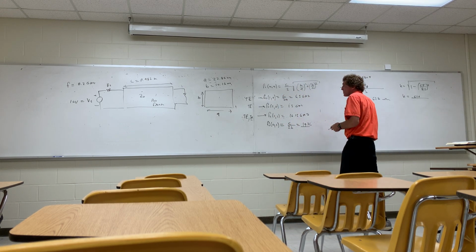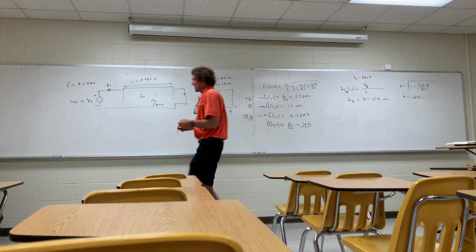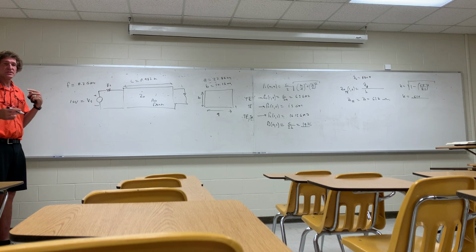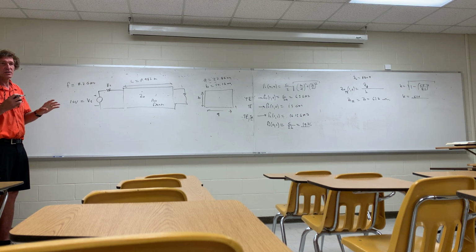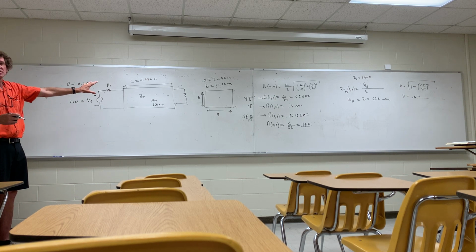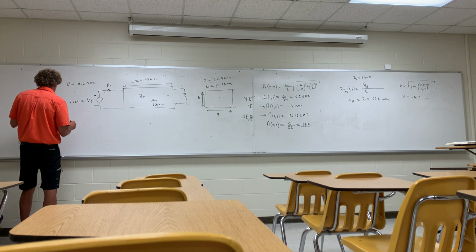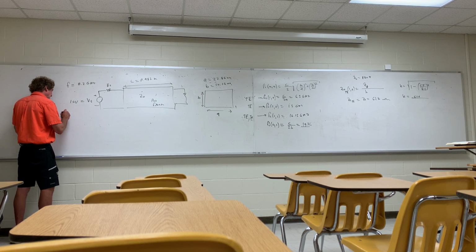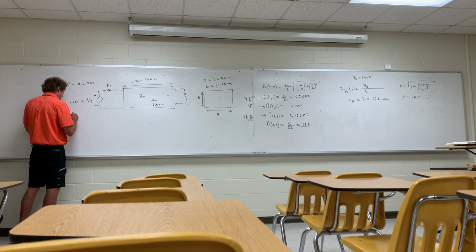All right, now, once we have that, what we have to do, because I know where we're going with this, we want the voltage at the load, we want the reflection coefficient, we want all the standard stuff, and now we're gonna start looking at this thing like a transmission line, not an actual waveguide. So the next thing we need is beta in the guide, right? Beta in the guide, and that's beta unguided, right, times K.